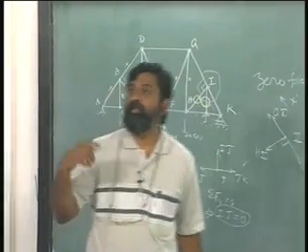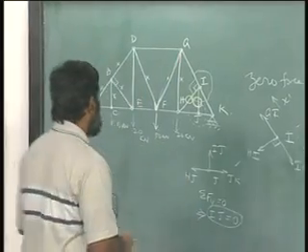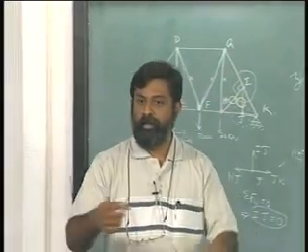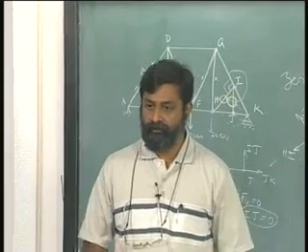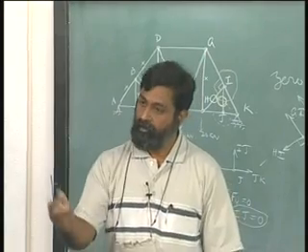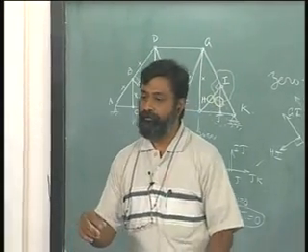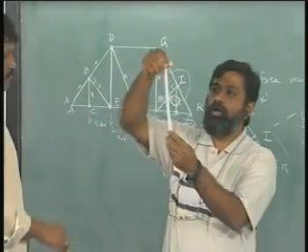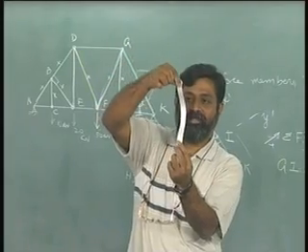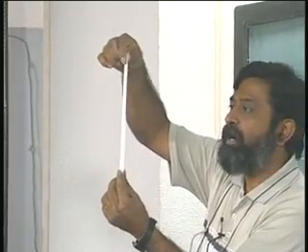That is when you need to understand the stability of these particular members. For example, can you give me a long sheet, a long strip? Yeah, you can come over here. So this is a long strip, let us say this is under compression. Okay, if this is under compression, it easily buckles, we call this buckles.